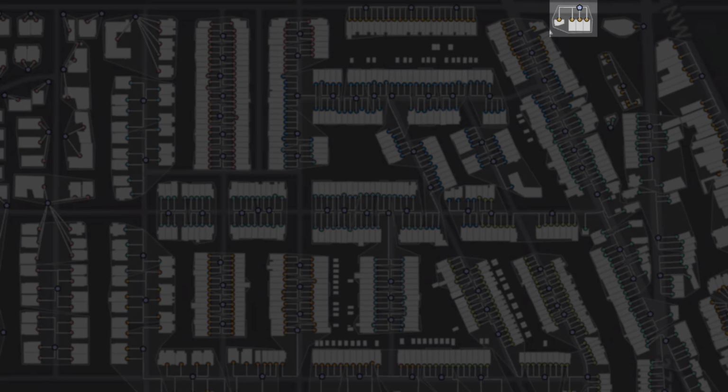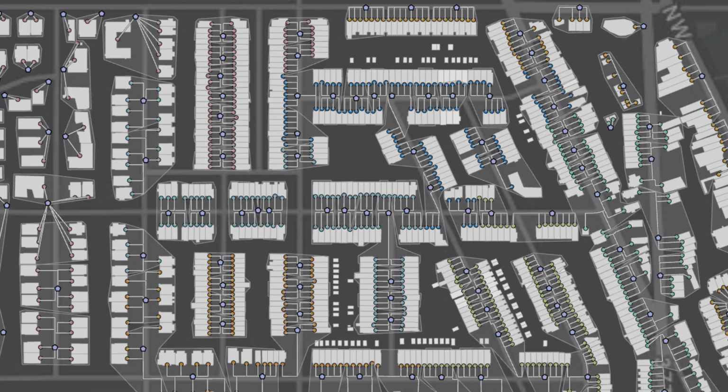Once that is finalized, Comsof Fiber Designer works on resolving the optimal routes for cables and ducts between that point and the locations to which it provides service. This too is governed by the rules operating on the available data. At this stage, one entire cluster has been completed. The software moves on, finds another set of locations to be provided service, and begins the process again.